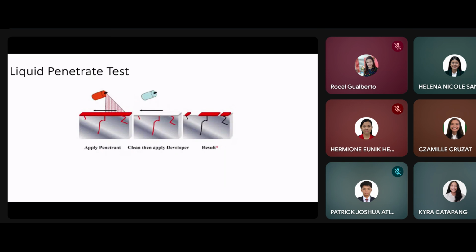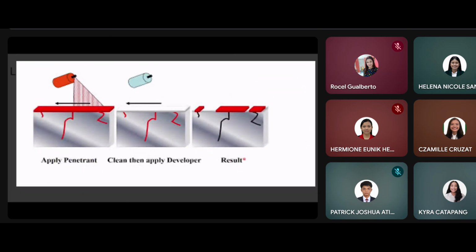Liquid penetrant testing. Liquid penetrant testing is one of the oldest and simplest NDT methods, where its earliest version dates back to the 19th century. This method is used to reveal surface discontinuities by bleed-out of a colored or fluorescent dye from the flaw. The technique is based on the ability of a liquid to be drawn into a clean surface discontinuity by capillary action.